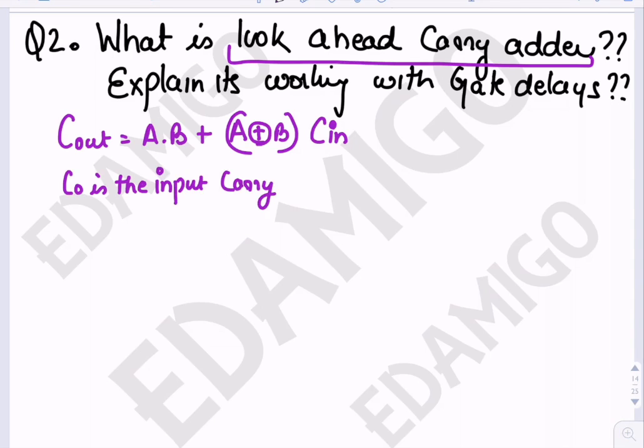Okay, so in the previous case we have taken there is no carry input, so let us take that there is some carry input, and in the 0th place also we are using a full adder. So we are not grounding the C0. As we have done in the previous case, we are just taking C0 as the input carry to the adder.